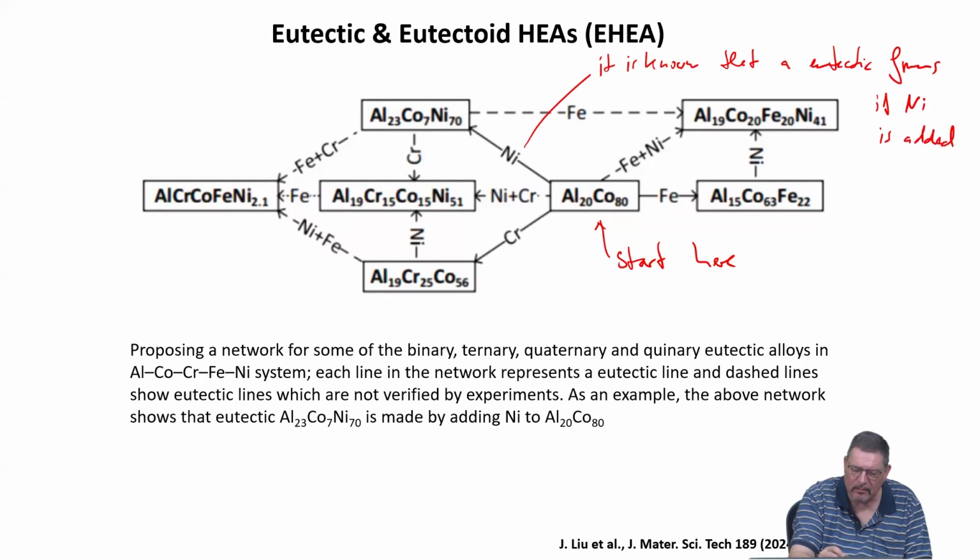Then you again know that iron and chromium with this, or if you would use chromium, you would get another eutectic. And this is why chromium and nickel have the same tendency for the formation of a eutectic, starting from the binary, and then iron is basically added without knowing it beforehand. So it means that you basically go from known eutectics, and then you add from binary to ternary constituents where you know that the eutectic is likely to form.